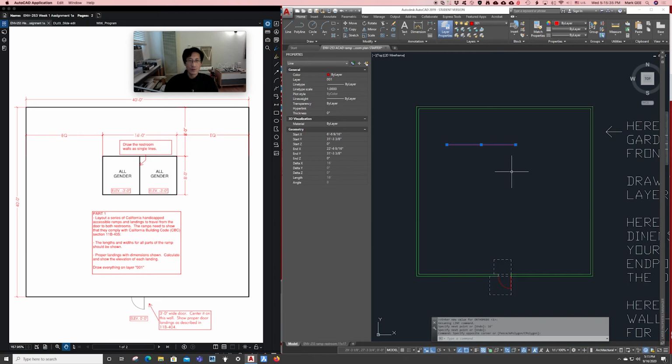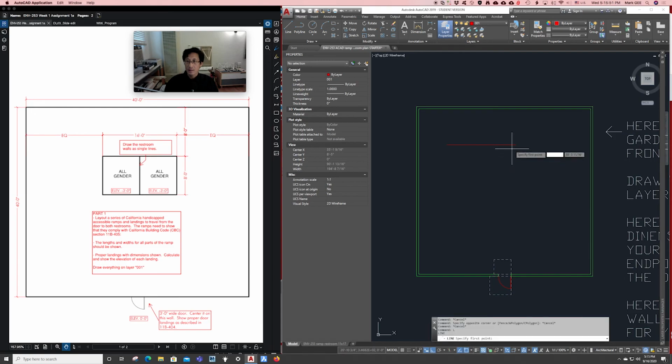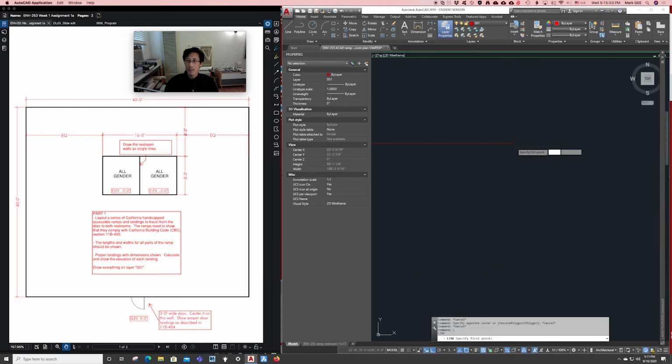All right, let's go around and do the other 3 sides. So we'll want 8 feet, then another 16 feet, and then back up 18 feet to start. Okay, so I deselect that line by hitting escape, and let's start a new line, L. Now, I'll zoom in here. When I hover over the endpoint of that first line, you see it gives me a little tooltip, with a little green square box, telling me that's an endpoint snap.